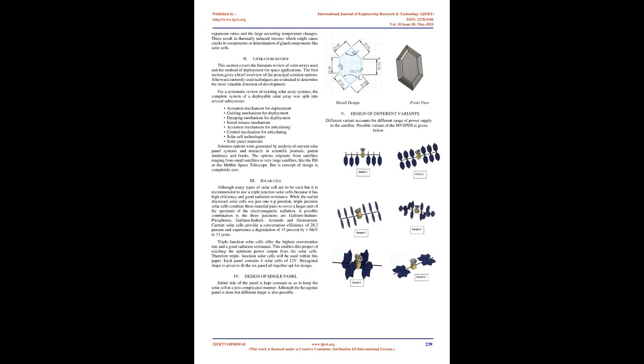The panels are usually in stowed position to avoid damage during the launch phase and are deployed later on when the satellite reaches its desired orbit. In general, mechanisms on board of satellites are limited to small dimensions and are required to be extremely lightweight by the satellite launch system. Working in an environment with no possibility of later corrections or modifications requires a high functional reliability and repeatability. The two major impacts on the satellite are the compatibility of the thermal heat.